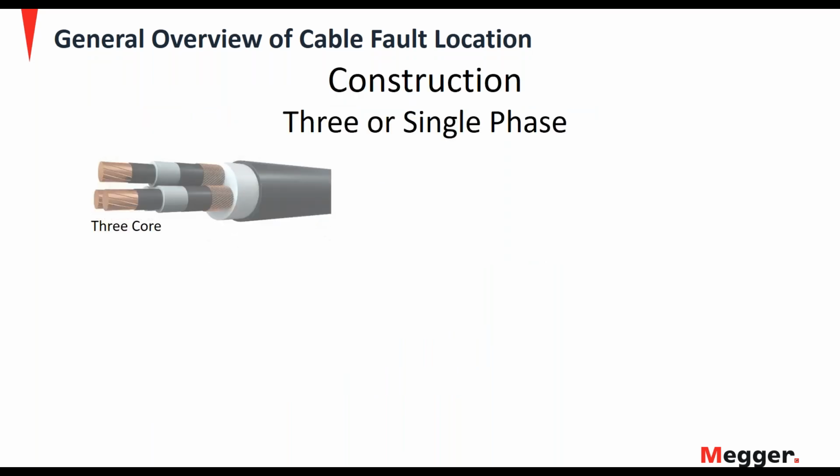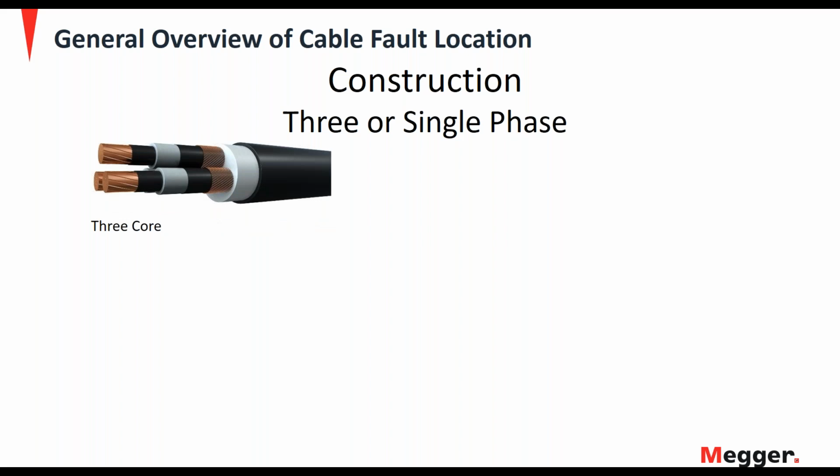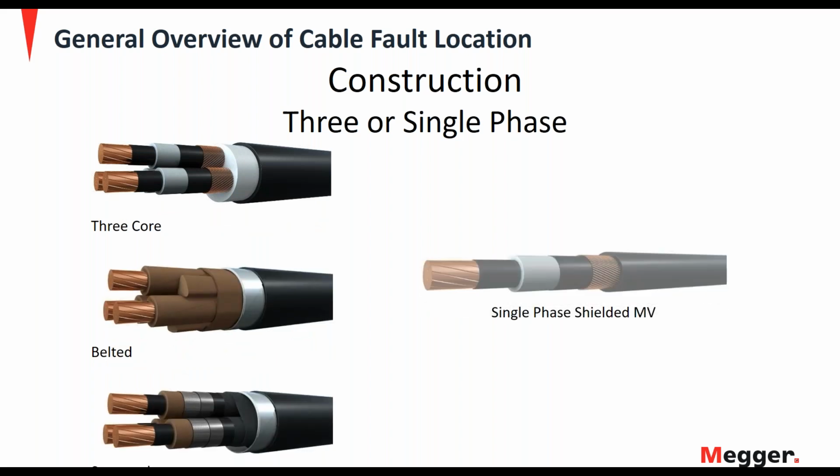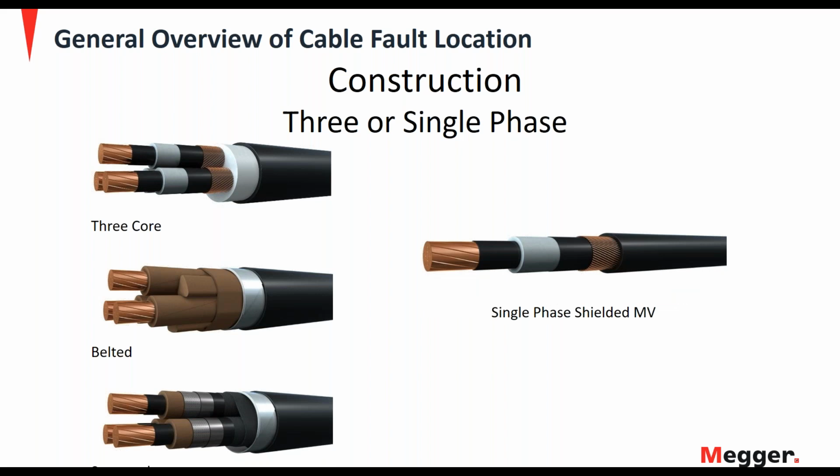What we're going to be focusing on more is shielded cables, and the construction could be of different types. 3-phase might be common. The single-phase shielded medium voltage cable, this is what we're going to be focusing on in today's webinar, and the arc reflection technique works well on these type of cables.